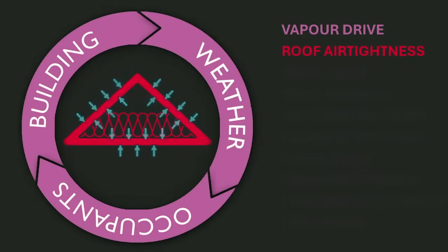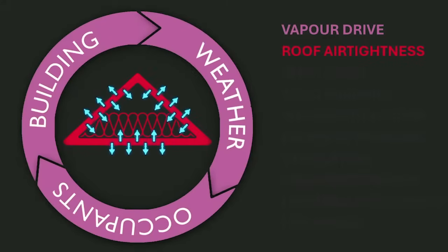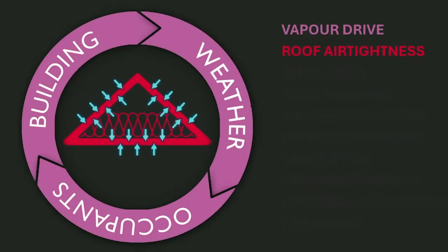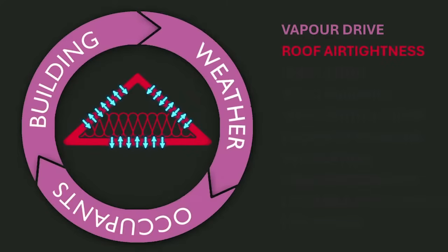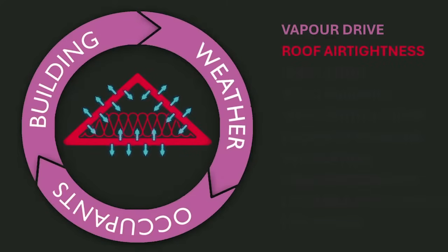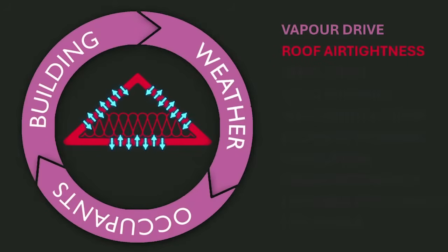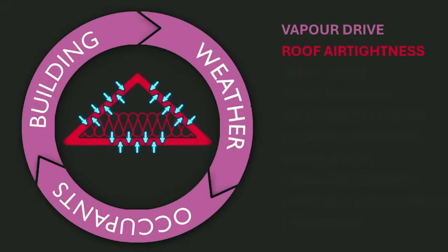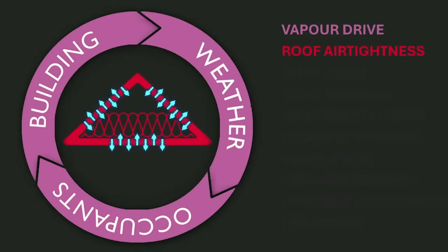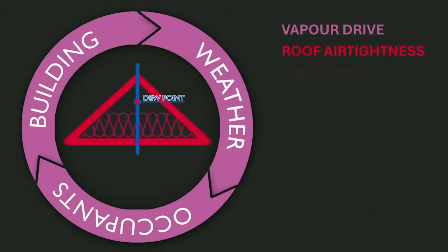Ensuring the transfer of warmer, more humid internal air is limited is also important, as air leakage can transfer moisture directly into colder areas, leading to localised condensation. Similarly, the air permeability of the outer covering must be considered, as roofs with continuous coverings such as metal sheets or photovoltaic panels will have a significantly different hygrothermal performance from discontinuous roof coverings, such as tiles or slates.